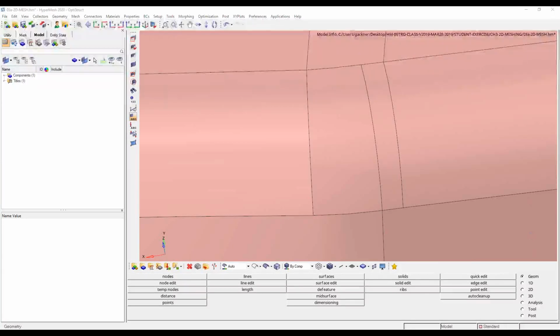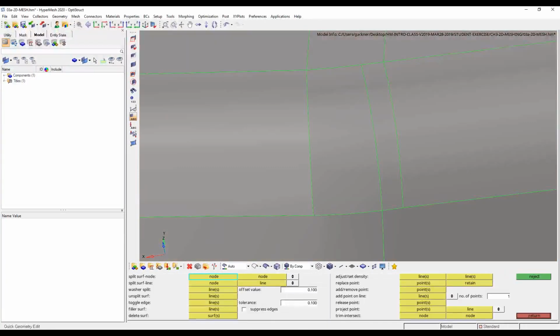So what I'm going to do here is I'm going to take my spotlight tool and go back to that geometry tool, and we're going to go to this little top corner menu, the quick edit tool. For you keyboard specialists, I'll put this in the chat again. The F11 shortcut key takes us to quick edit, and F12 takes us to auto mesh. That's a very convenient pairing. Let me put it to everyone, not just Darius here. So F11 is a shortcut for quick edit. F12 is a shortcut for auto mesh.